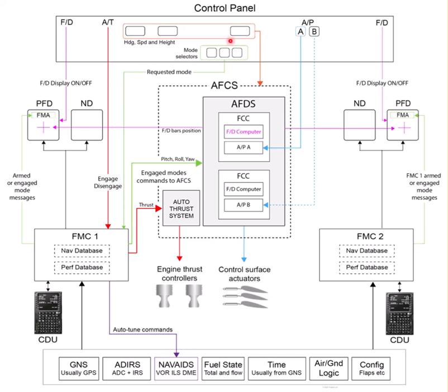Now I haven't pressed any extra buttons up here other than engage autopilot. So whatever modes I see on the FMA, what's happening now is, of course, that instead of me, the pilot, having to fly them, the autopilot does that. And I can cross-check that the autopilot is doing the right thing by monitoring the flight director. Clearly we have to monitor everything, we have to make sure our altitude and speed are still correct, but assuming they are, then the flight director should be showing us what's going on.